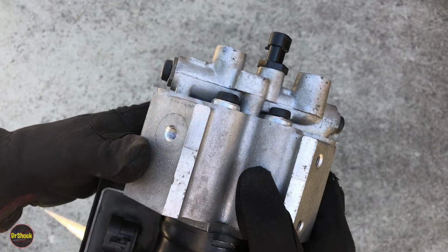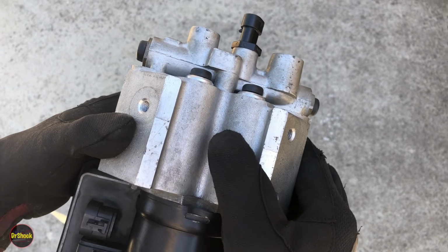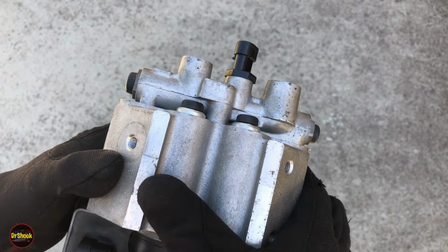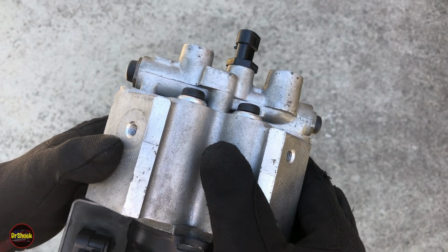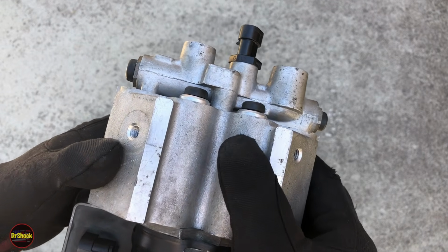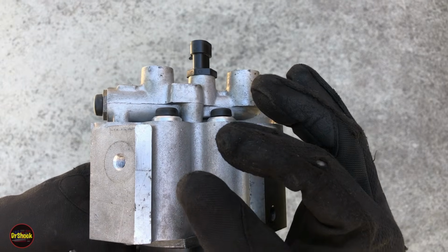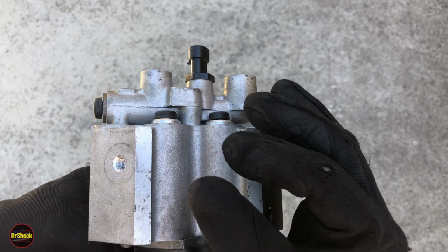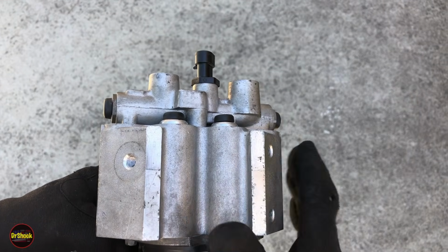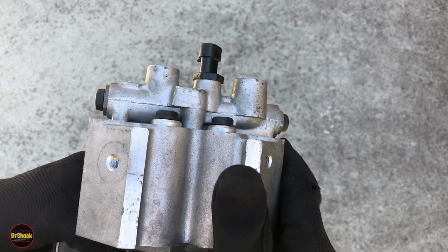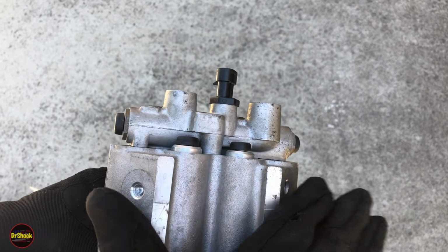The pulling to the left or the right is similar with the internal valves. They're not responding fast enough, or they're sticking. And that's going to get you pulling to the left or the right. You've got to eliminate the problem being an issue with the front brake line, because that's the more common problem with pulling to the left or the right. The brake line, the soft rubber part, is actually a two-piece design, and internally the inner piece could collapse a little bit, and that can cause that problem. Or you can just have a seized up caliper that's causing that pull to the left or the right. But if you've eliminated those, then you end up with this problem here.